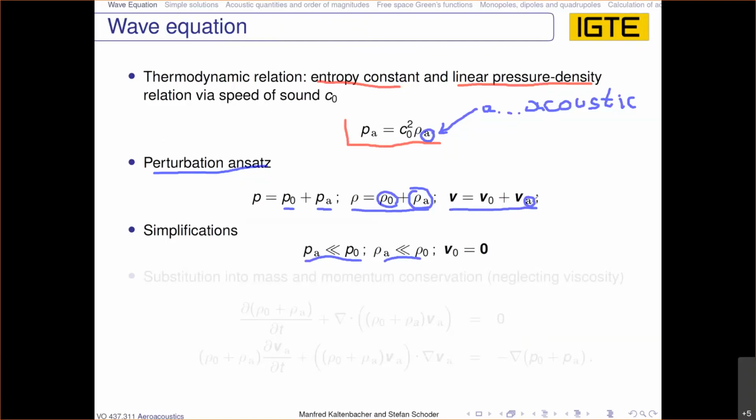And as you see, we call it in English quite correctly acoustic particle velocity. So really the particles in the flow, how they move, with which velocity. You know, in German, we call it Schnelle. So we just have in German our own word for this particle velocity. And here we even assume that you have no background flow, so our V0 as seen here is 0.